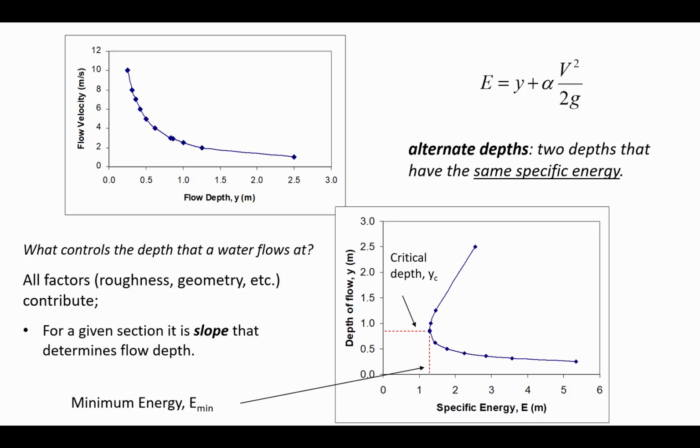If we were meeting in person, we'd go down into the fluids lab and we'd fire up the flume. And we would look at the hydraulic jump. I may have to make a video of the hydraulic jump and show you what happens. But the flow can be supercritical and then jump up to its subcritical alternate depth.